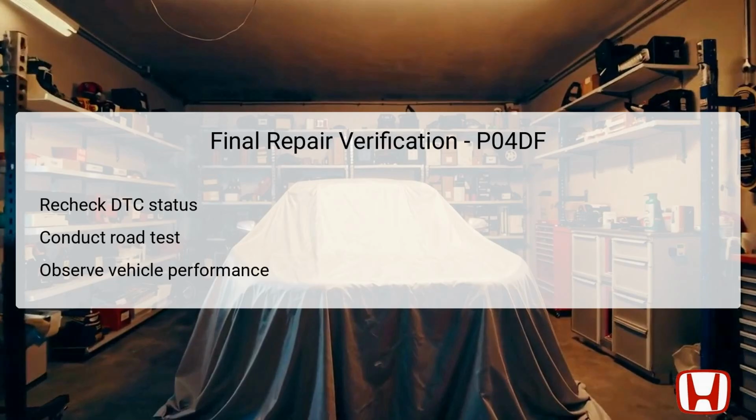Pay close attention to the functionality of the EVAP system during various driving conditions to confirm proper operation. Observe any symptoms like rough idling or engine performance issues that may still indicate underlying problems.